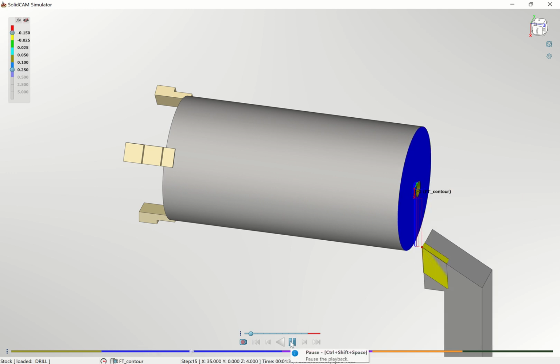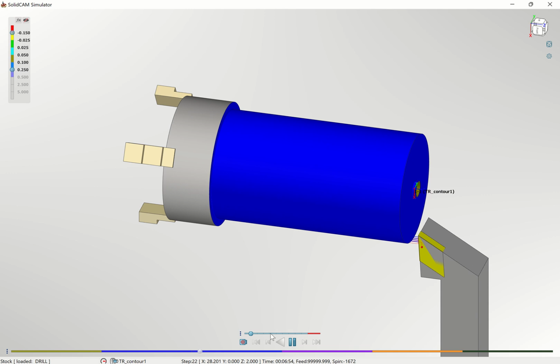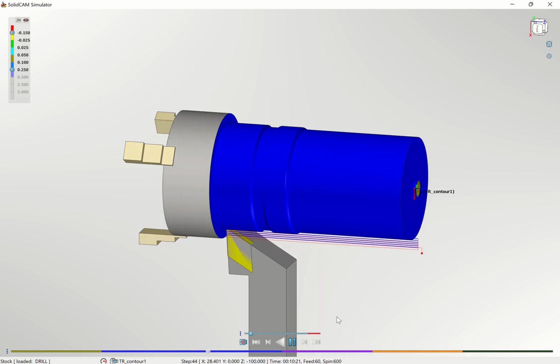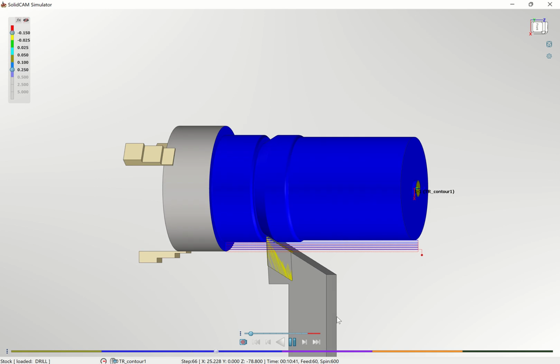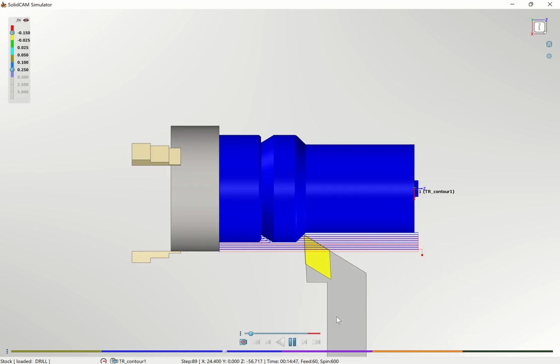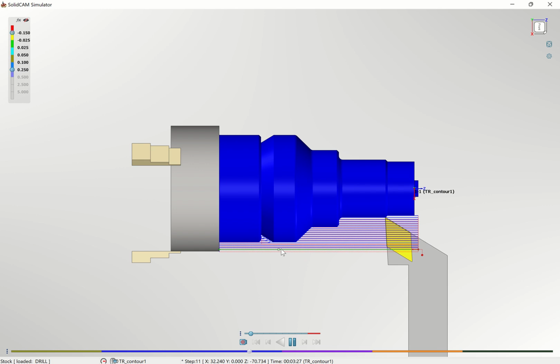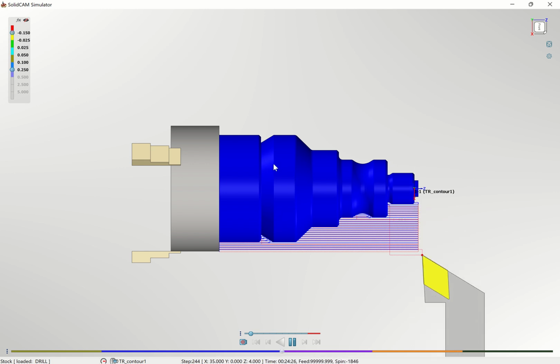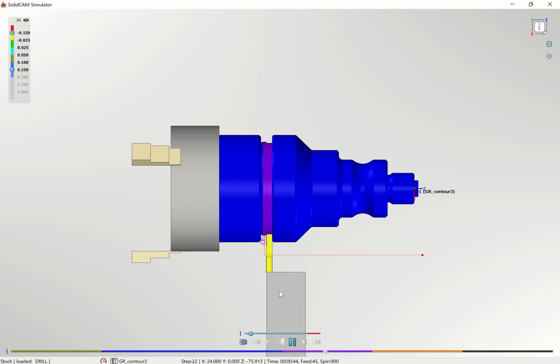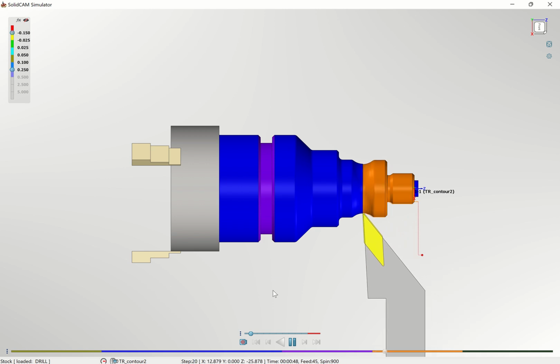So that is what it's doing now. Yes, you can see what it's doing. That is a rough turning. I've also set it so that in case of any groove, it will do an actual groove turning, so that it goes where there's material for grooving, but where the tool cannot plunge into, it will leave an extra material. That's why here you're supposed to be grooving, but it has left some material. So the grooving tool will easily come in and finish the material, without machining from the start.